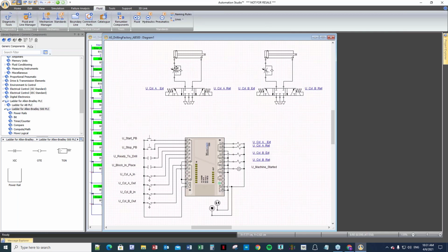Now I added this area, this point over here, just to refine a little bit in controlling the speed on the cylinder, by restricting the airflow. By the way, I'm not a pneumatic expert, so I think this should do it to control the flow. You can refine on that because you know the subject in pneumatics better than me.